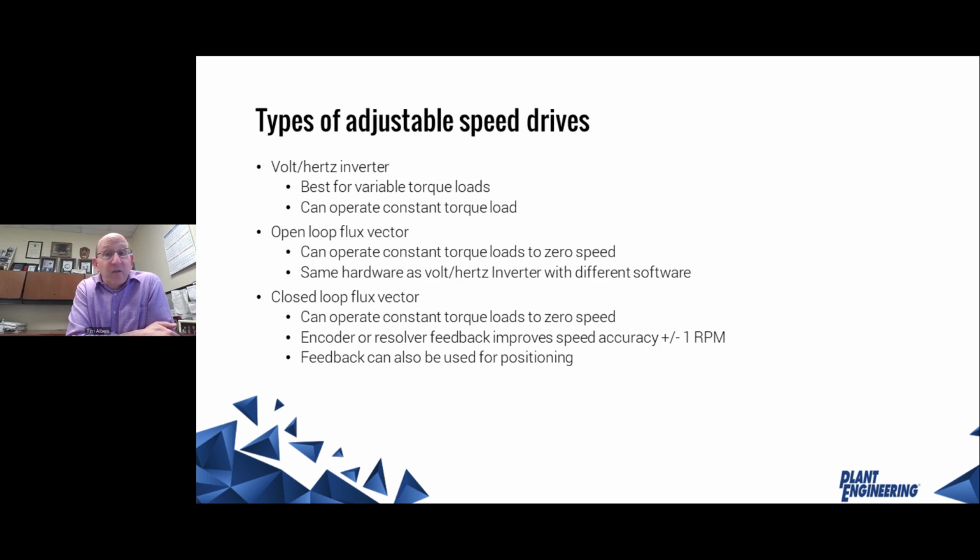These are the easiest drives. They don't have, in many cases, all the complicated instructions and things like that. When it says volts per hertz, it's designed so that if it's 460 volts at 60 hertz, then it's half, 230 volts, at 30 hertz. It just does that. It doesn't necessarily have a lot of capabilities for high-end machine controls, but for a variable torque load like a pump or a fan, it's perfectly suited for that and will do a great job.